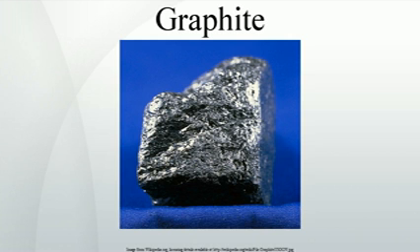They are then extruded and shaped, baked to carbonize the binder, pitch, and finally graphitized by heating it to temperatures approaching 3000 °C, at which the carbon atoms become arranged into graphite. They can vary in size up to 11 feet long and 30 inches in diameter.